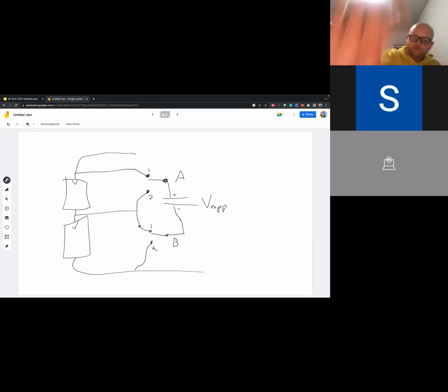And then by switching really fast between position 1, position 2, position 1, position 2, you make sure that both solar cell voltages are equal to the capacitor voltage, and because of that, the solar cell voltages become equal to each other, and because the maximum power point voltages are the same, this works. And then on average, you will get your 2 amp here.